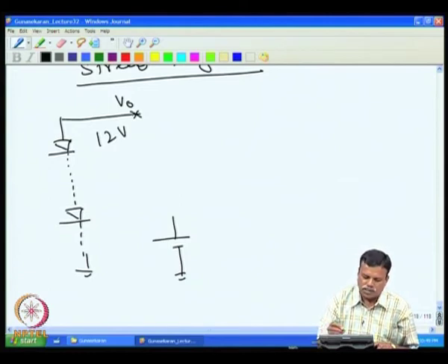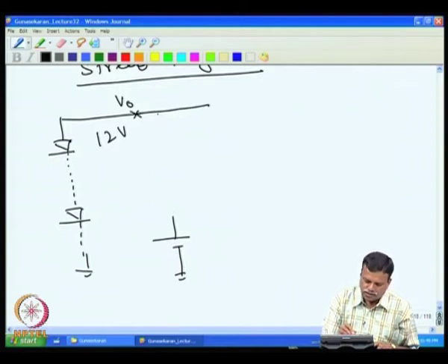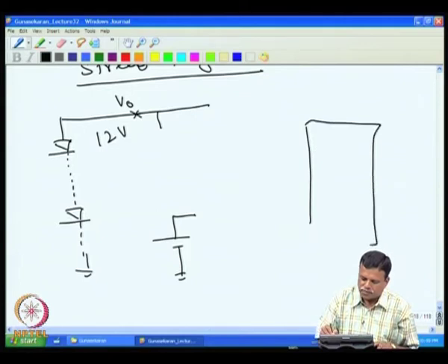Similarly, if the voltage is more than, say, 5 volt, then we can assume that there is sufficient light and the lamp should go off. So, it is essential that we sense the voltage of the panel and the voltage of the battery, both using the ADC present in the microcontroller.